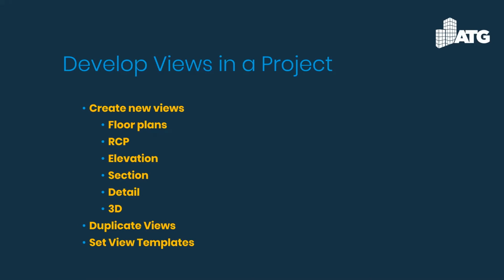You can just simply duplicate the view, which duplicates it, but it doesn't bring any annotation over, which is what a lot of people will do, because if you're creating a new view, you typically want to show different types of details, different annotation anyway. So the duplicate view is, again, the one that most people use. If you use the duplicate view with detailing, then it will bring over all the same exact annotation and give you an exact duplicate of that.